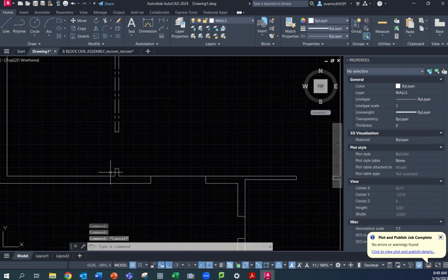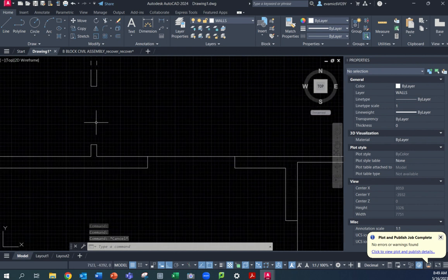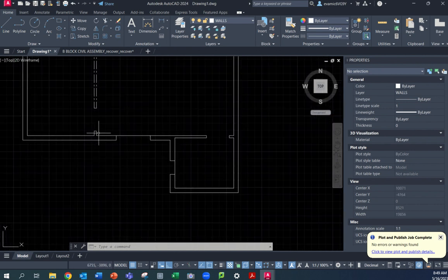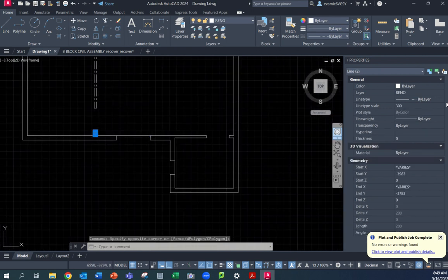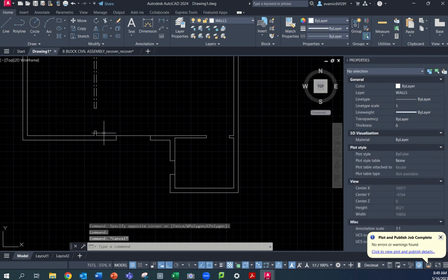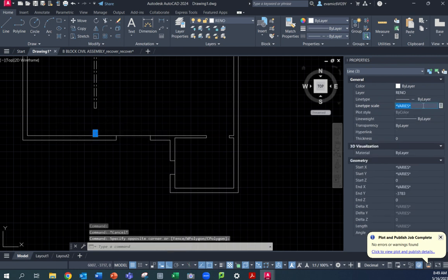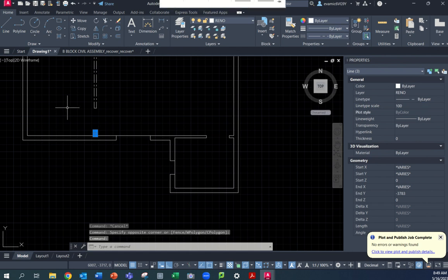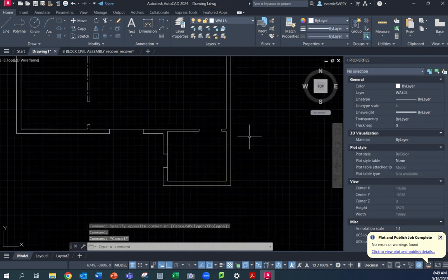That gives us the detail we need for wall removal. Only problem here is it's not given us enough detail there, so I'm probably going to drop that down just to that one, particularly to 200. Still doesn't show it for us, so we'll bring that down to 100. Enter. Let's see what happens here. There we go. It shows it there.